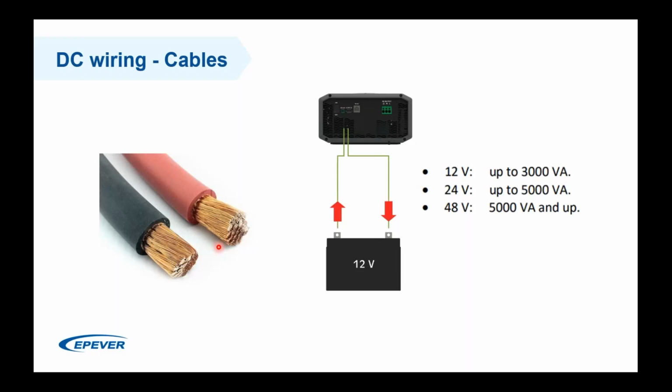And on the other hand, if you cannot find thick enough cables in your system, you can use double cables. In some inverters and charge controllers, you might see 2 positive terminals and 2 negative terminals for the batteries. The reason is that the specific unit provides high current, and it's a high power unit that demands higher thickness. So the trick is to use 2 terminals as positive and 2 as negative on that inverter charger, for example. With this trick, you can still use the same thickness, but you are doubling the cables that you are using in the system.